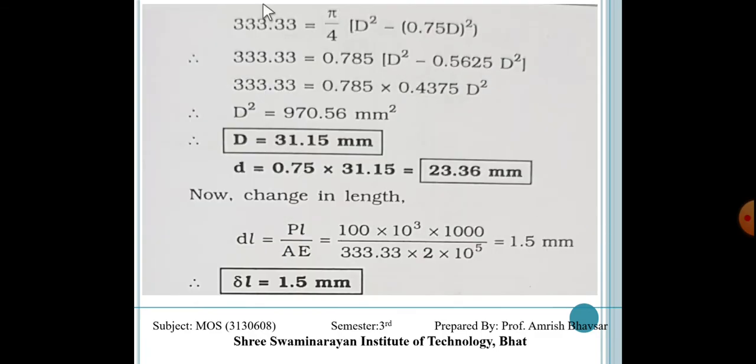So from this equation we will get capital D square is equal to 970.56 mm square. Here we have to put small d is equal to 0.75 D square. So now using the calculator we will get D is equal to 31.15 mm. So small d is equal to 23.36. Now we have both the diameters, external as well as internal.